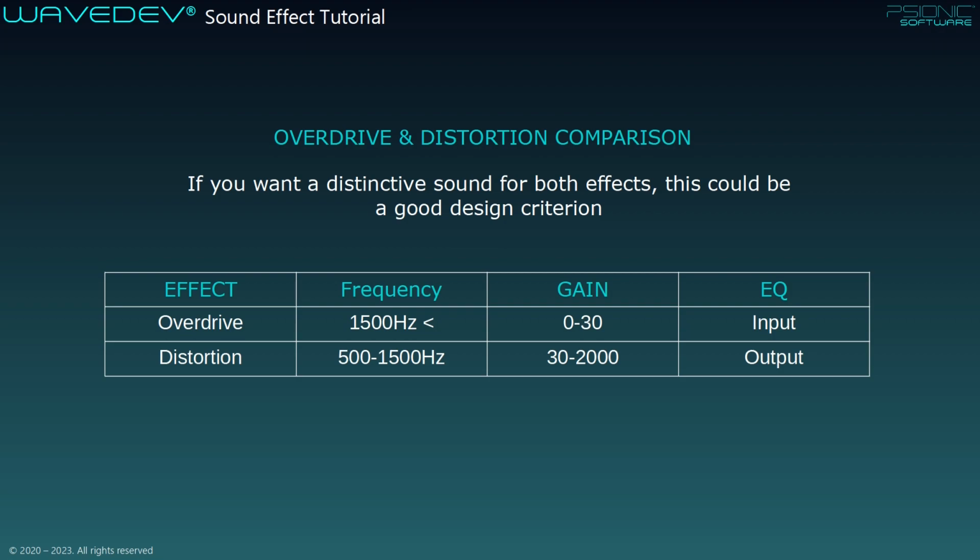I suggest you use a fixed input equalizer for the overdrive effect. But try to improve the tone control to achieve more coloration and not just attenuating treble. Remember that the overdrive generally precedes other gears. That's why I didn't apply too much filtering to the output of this effect.